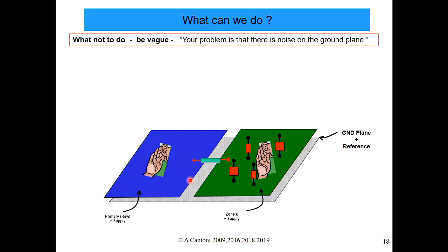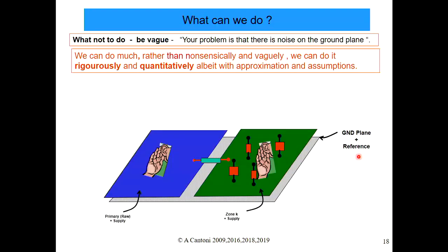Generally, when you transmit signals from one point to another, it's not just one wire, it's a potential difference with respect to a reference. So the actual signals are some voltage with respect to a reference, which is typically the ground plane. If there's noise on that reference line, then the actual signals may be interpreted incorrectly and may cause the system to fail. So noise is often a significant issue in designing particularly high-speed systems.